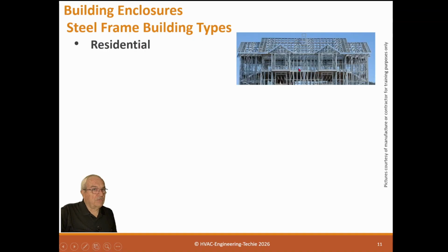Steel frame buildings, we do see some steel frame for residential. And this is fine because they're much more fireproof and termites don't bother them at all, which is a good deal. However, they do have a couple of problems. Having followed this and been involved in a few, they do make noise. What happens is the expansion and contraction of a normal building, like your home. If you're in your home, you'll hear it crack, creak every once in a while. That's because it's expanding or contracting. Well, metal buildings squeal when they do that.